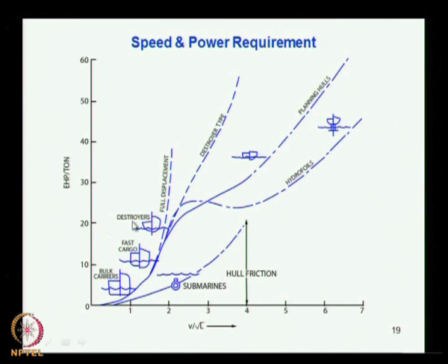If you look at the other type of vessel, this is a destroyer type which is finer in shape, again also under the displacement type, whereas these two vessels are deep displacement. This is not so deep displacement. Then you consider another vessel called planing craft. Planing crafts are ones having a hydrodynamic effect. Maybe I should give you a picture of that in another class, maybe when we discuss the resistance of advanced vehicles, we will see that.